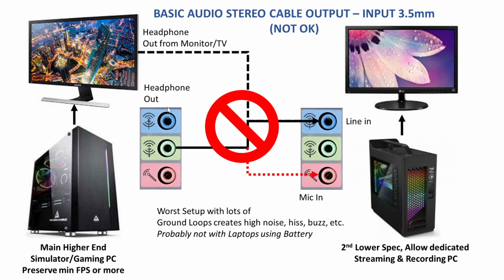So whatever you do, it is connecting the audio and the grounds, right? What happens is that the power from each of these PCs creates another ground. So it creates loops and it multiplies the electromagnetic noise, basically. It's like multiplying several times, and you hear a very annoying hissing noise, buzz, hiss, whatever it is.